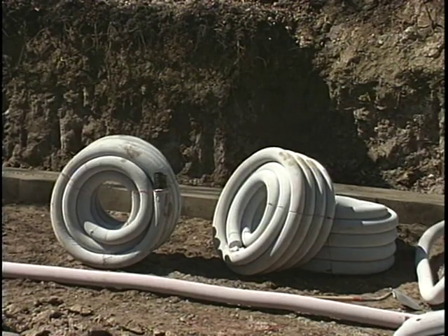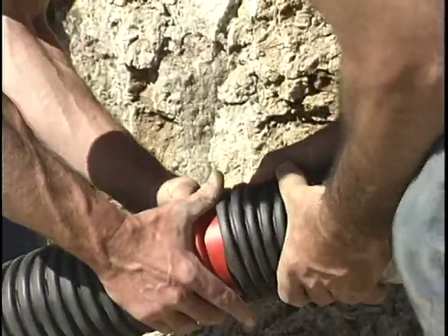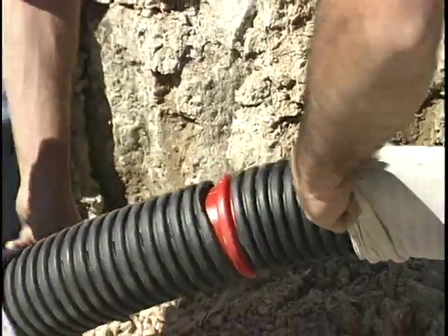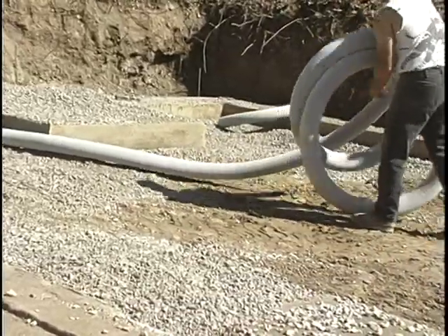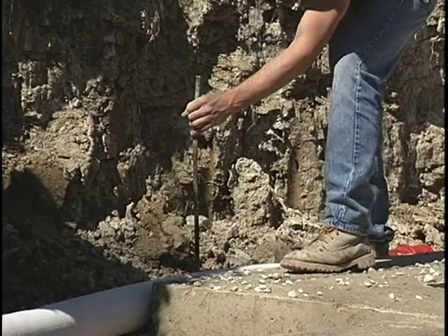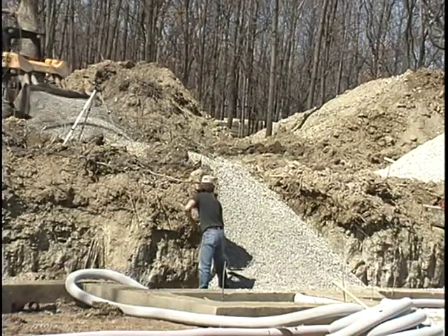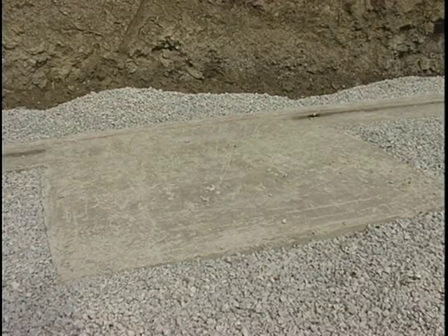Modern drain tile or pipe is usually a perforated, cloth-covered plastic hose that helps protect the foundation from water seepage and possible damage. The drain tile hose is run along the outside of the footer and covered with rock. The drain tile, using gravity or a sump pump, carries water away from the house or to a sewer.